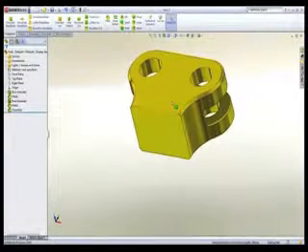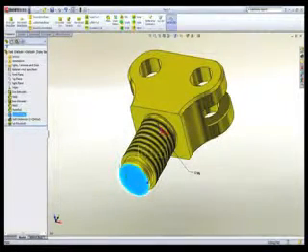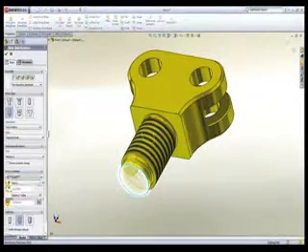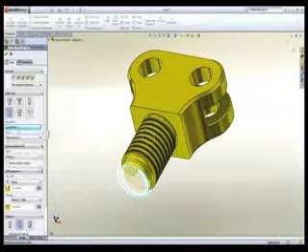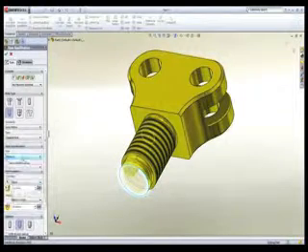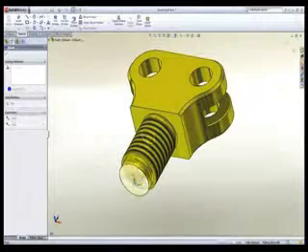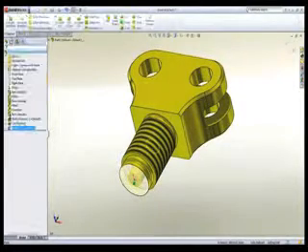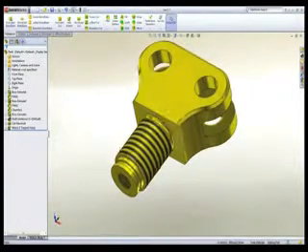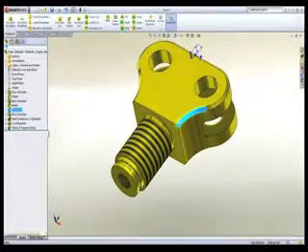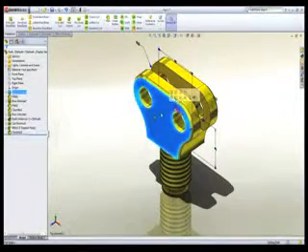Now that you have the hang of it, we will jump ahead a couple features and add a tapped hole at the bottom using the hole wizard. Gone are the days of looking up hole data, because all of the hole types, standards, and hole sizes are available. Choose the hole parameters, locate it, and SOLIDWORKS takes care of adding all of the proper information to define the hole. Let's leverage our previously created chamfer by dragging and dropping it onto the bottom edge to make a copy. The part looks good, but maybe a couple of changes would help to refine it.